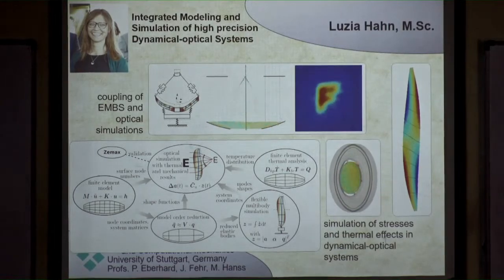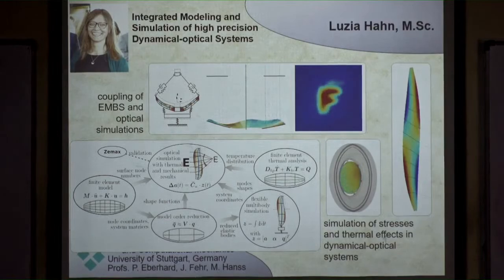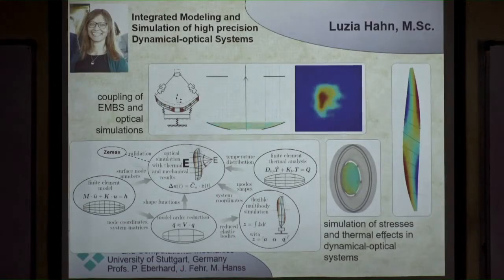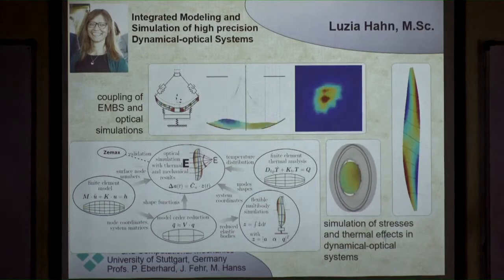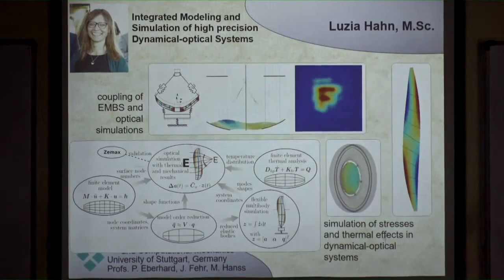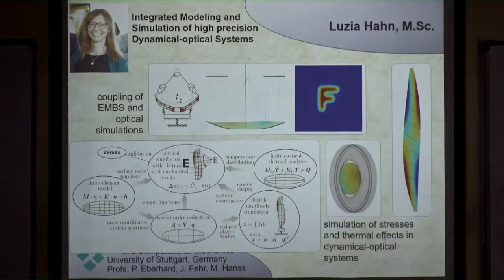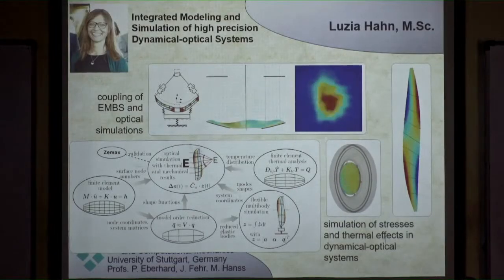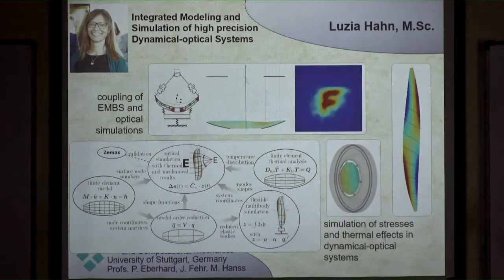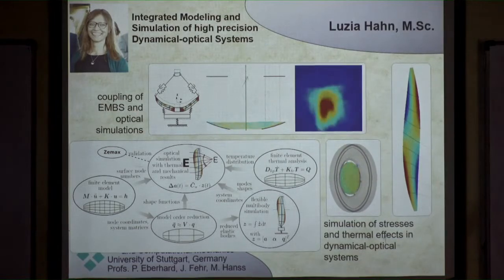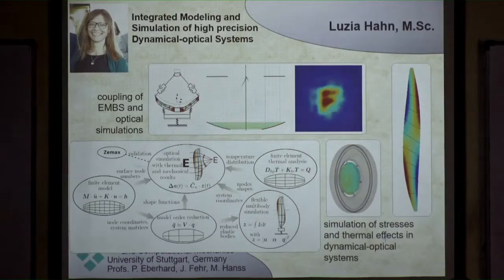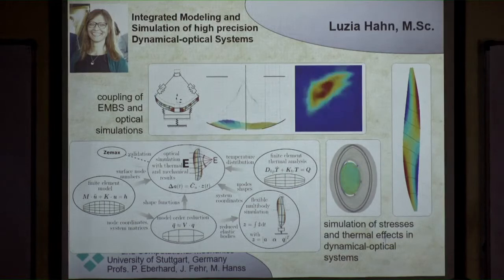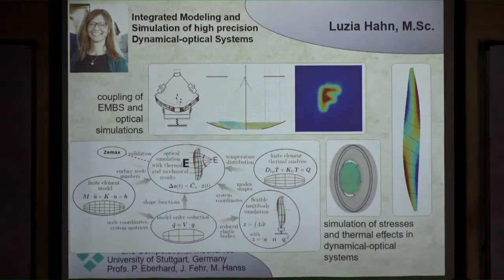So therefore, you are at the absolute limits of physics. By the way, modern chips are not always produced in this way. Why? You want to make the structures smaller and smaller and smaller. But there's a physical limitation. If you want to make the structures smaller, you want to make the wavelengths of the light used smaller. Therefore, you go from red light to violet light and so on. But if you further reduce the wavelength of the light, suddenly glass is not transparent anymore. If you look through this glass, it's transparent, I can look outside. But if you want to send a ray of ultraviolet light to this, it's blocked, it cannot pass.